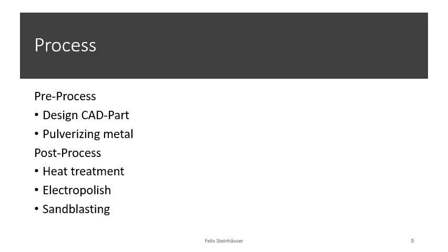Then after the 3D printing of metal, you have to do some processes to finish the surface or the properties. First of all, you have to get rid of all the excessive metal powder that is not fused to your metal part.